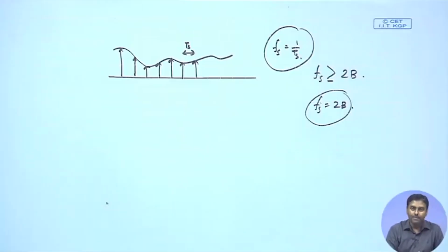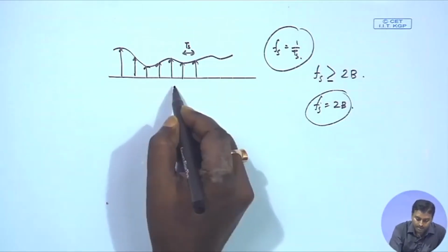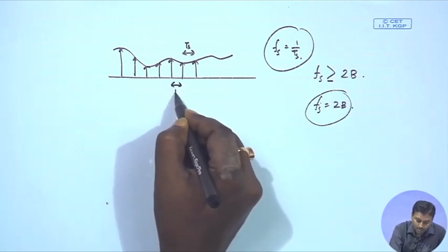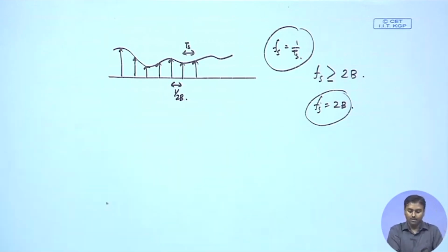Okay. So, that is something which is required, because otherwise there will be aliasing again. If the highest frequency does not have any significant power component, or any impulse or any kind of carrier, and I just sample it at 2B, then what will happen? Fs becomes 2B and Ts becomes 1 by 2B. So, this is something I already know.